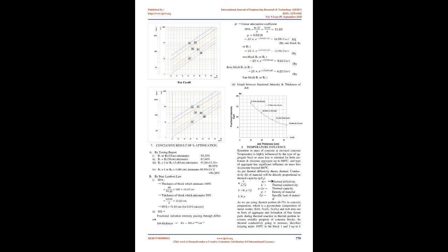B. Principle of radiographic testing. It is based on the principle that radiation is absorbed and scattered as it passes through an object. If there are variations in thickness or density in an object, more or less radiation passes through and affects the film. Exposure flaws show up on the film.